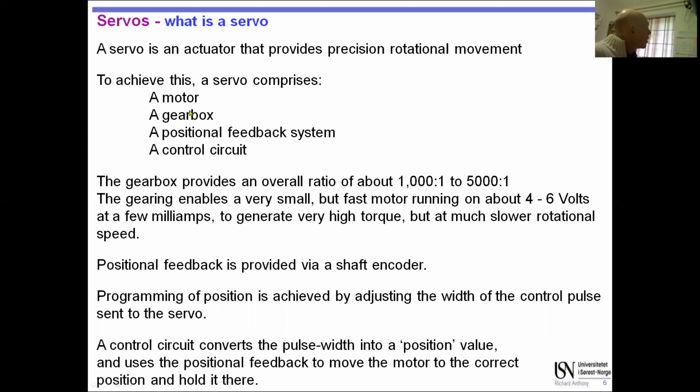So we need a gearbox so we can slow down the motor but also increase the power output. A small motor turning quickly can go quick, but it doesn't have much power, much force, much torque. The proper word for rotational power is torque.